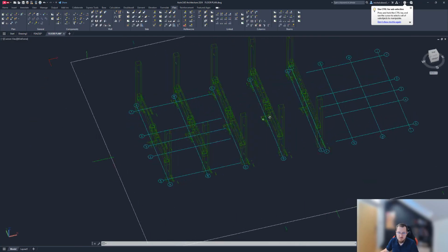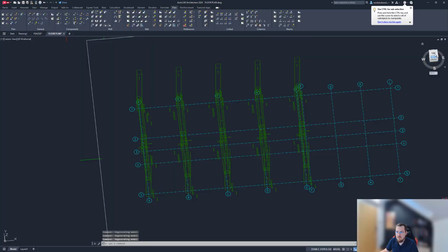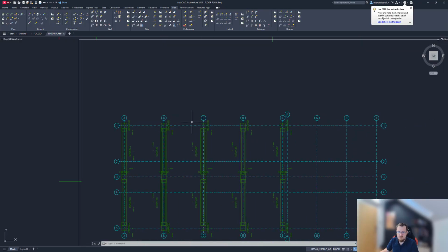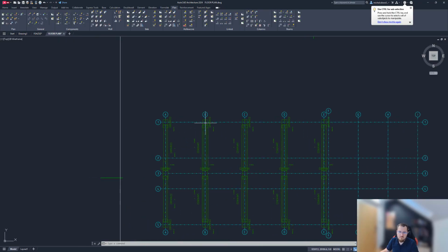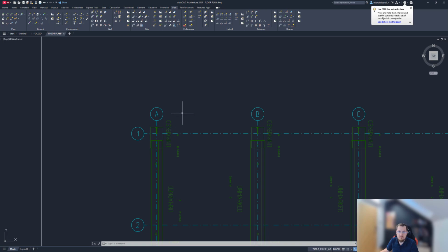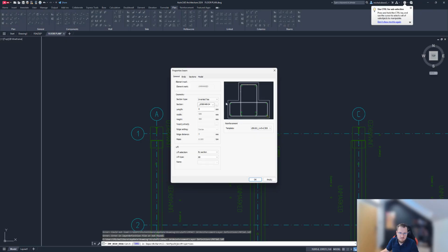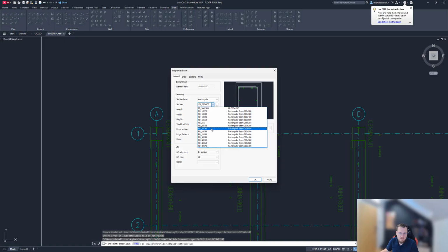Nothing stops us really from, of course, adding some additional beams for stability in the other direction, just so those are not really individual frames. So really not an issue. We can just go ahead, for example, draft those beams at a different level, some stability beams, just your rectangular ones, like that.